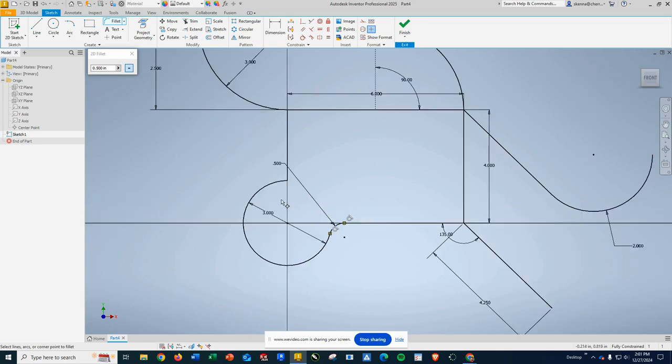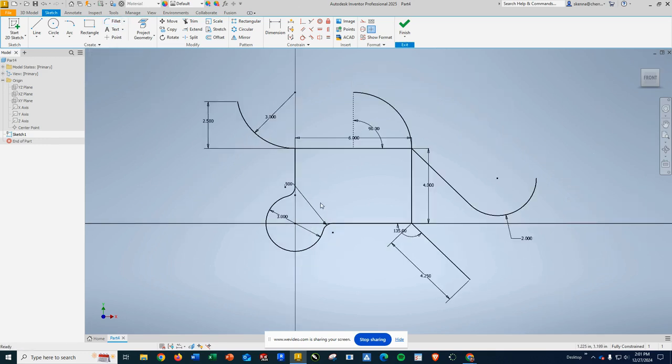Okay. And I'm going to do the same thing up here. So this arc and that, so that those curve in. And when I'm done, I can go ahead and apply those. But that's what a sketch fillet does. I'm not really going to use the chamfer, but the chamfer works just the same way. You'll have some settings and you'll be able to click a corner and have that happen.